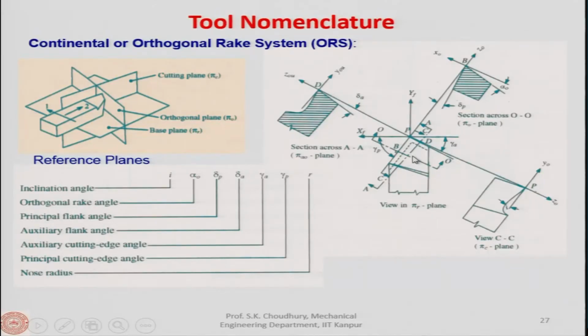So, the rake angle has to be established again, because it is spoiled, it has been rubbed off by the chip. So, the wearing action has taken place, or the rake face or the flank face has been worn out. So, the tool, when it is reground, has to be placed on the grinding machine according to the angle at which the tool will be working, working angle we call it. So, those working angles do not coincide exactly with these angles which define the inclination of the rake, flank and the edge angles.